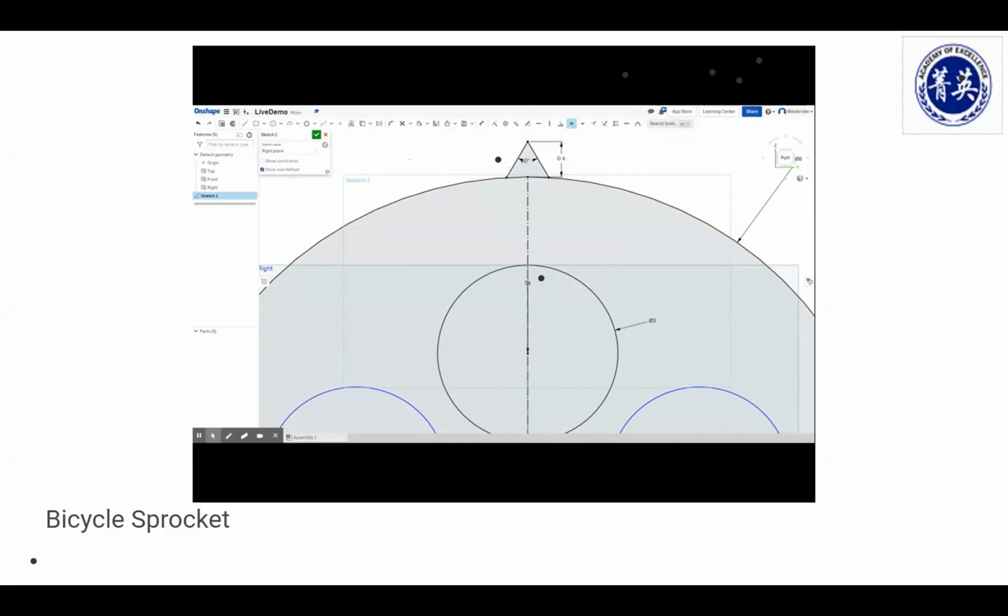Good. Now gear teeth are not really sharp at the very tip. So let's put a little bit of a radius on the very top. Let's call that 0.05. Oops. That's the wrong one. Let's do that again.